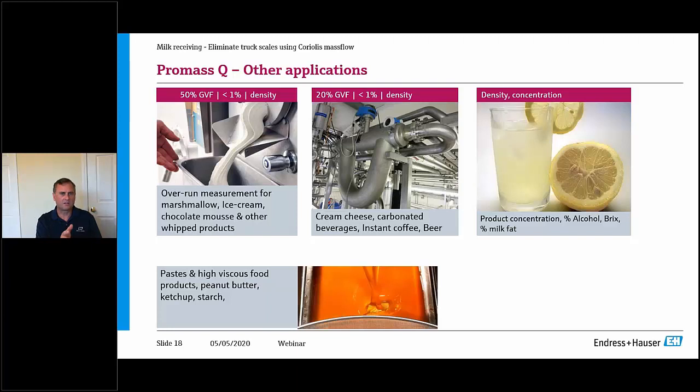Traditionally, with Coriolis meters you'd say, nope, I don't want to do that. It just didn't work very well. With the ProMass Q, it works fantastic, and we're getting to a point that, say for the ice cream overrun measurement, using 2 pressure transmitters as well, we're actually able to tell you, as a quality parameter, how much entrained air, how much overrun you actually have in that product.